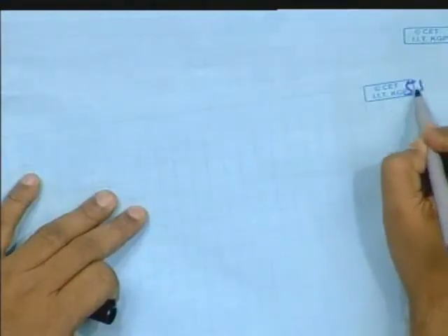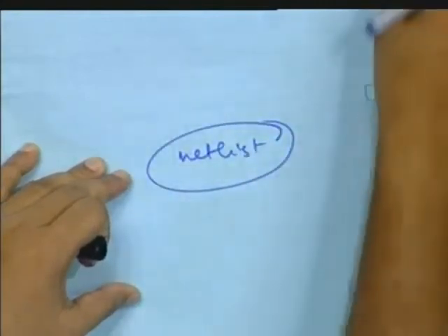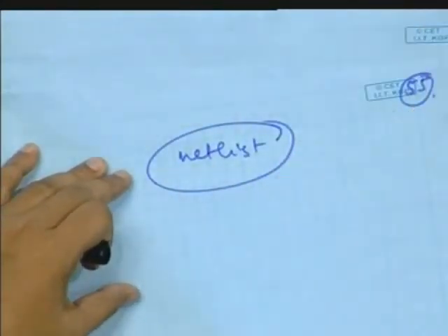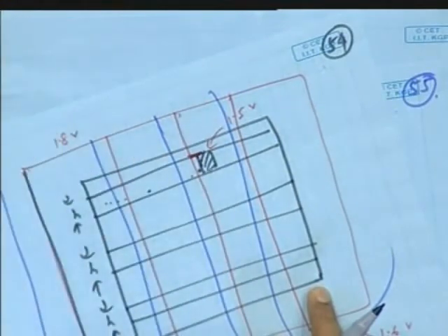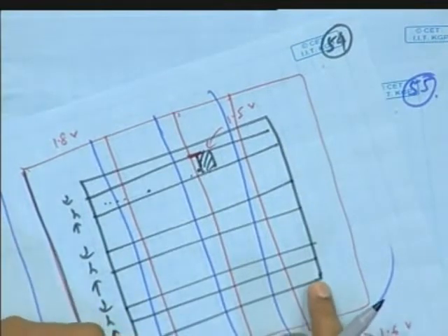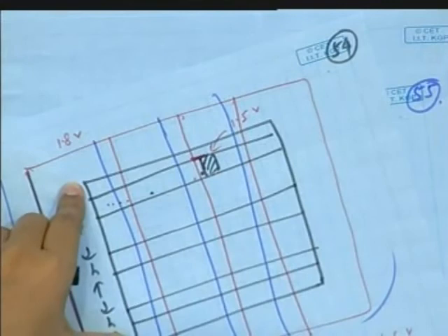Once these are all done, what you do is you take your netlist. During floor planning also you have to have the netlist in your hand because all these things you are doing with your netlist only. The area it has to take. For example, this core area, either you have an already existing footprint because you are working in a company and they have a market, or for your own case maybe it has to be defined by yourself, right? This W and this. In the script probably you have seen I have defined 200 200, the width and this.